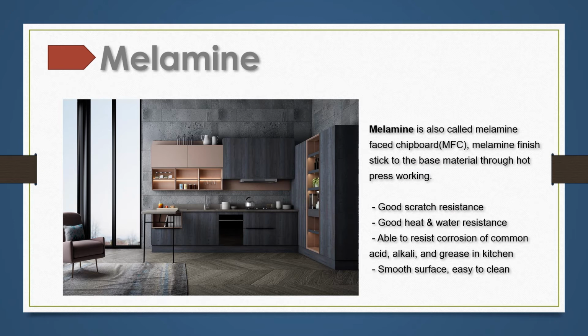Preform finish is literally what it means. We have the finish preforms with all kinds of colors, grains, glossiness. We stick this finish to the front and back sides of our big boards, usually particle boards. We cut the board into smaller panels we want and use PVC edge bands to cover the four edges. The edge band is 1 mm thick and its color and grain will be similar to the front finish.